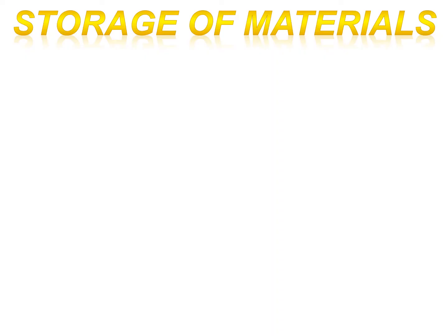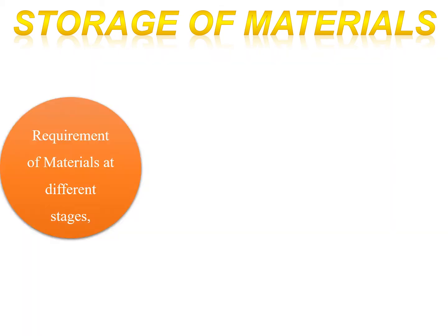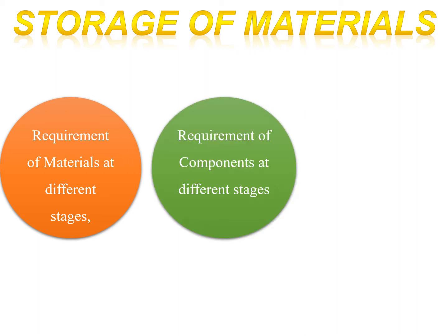When you say storage of materials, for any site there should be a proper planning of the layout for stacking and storage of different materials, components and equipments with proper access and proper maneuverability of the vehicles carrying the material. While planning the layout, the requirements of various materials, components and equipments at different stages of construction shall be considered.